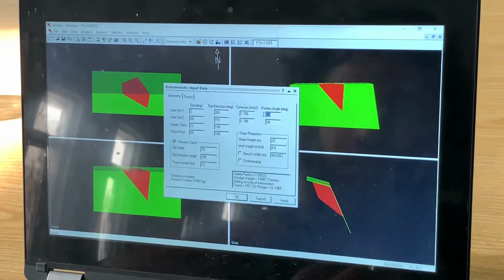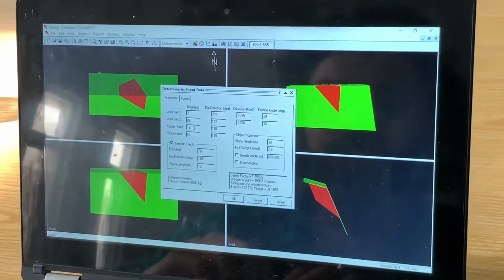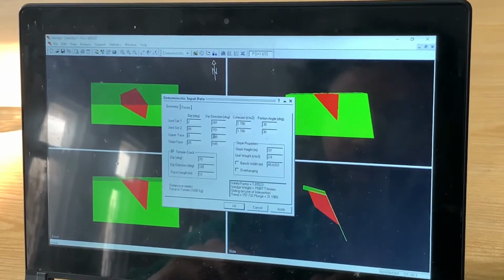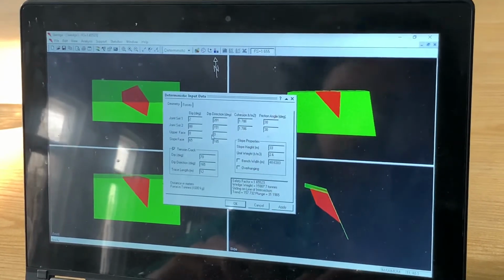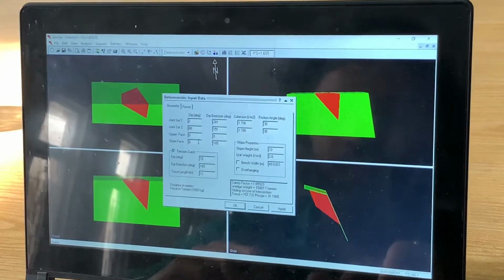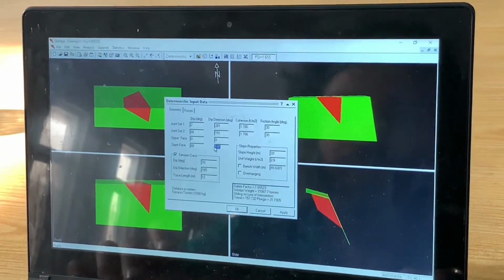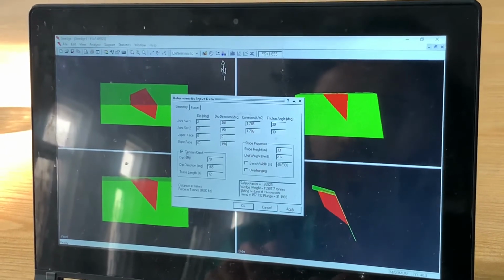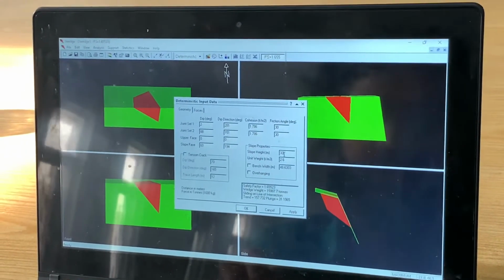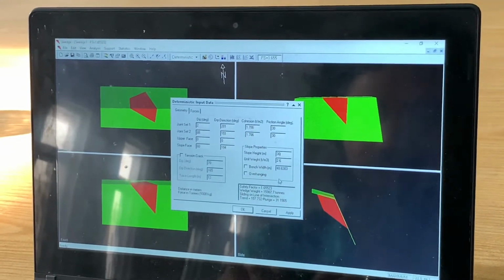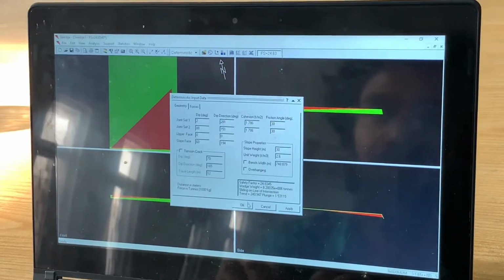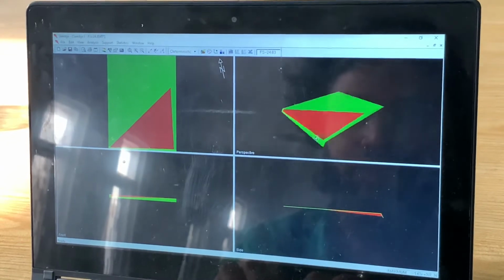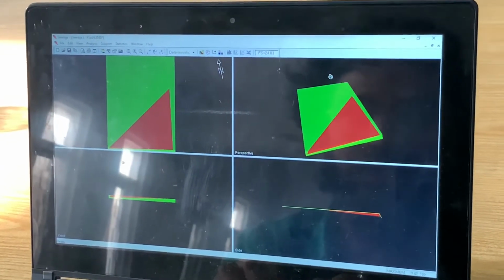As you can see, the friction angle here is 30 degrees because the friction angle is calculated for sandstone. The upper face is not present, so we will put 0 for it, and the slope face we have calculated 60 and 194. As you have seen, there is no tension crack, so we will uncheck it, and the slope height is maximum 30 meters and unit weight is 2.6. So we will apply it, and you can see here we have got the wedge failure from top view, front view, side view, and here is the perspective mode. You can see it from various sides.